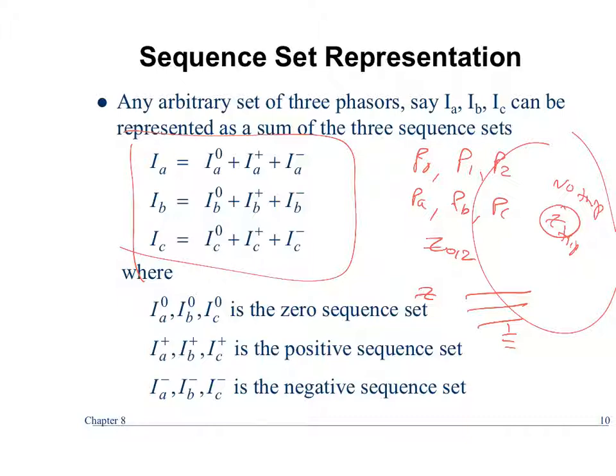Ground fault is so bad for using that you don't just rely on this 21 element, which is called, is it an impedance element? It's actually a distance element because how far you are away from a fault, right? So I'm a relay here sitting here monitoring for a fault. The impedance of the system changes as the fault occurs, right? When you see a load, there's a V divided by I, right? I get an impedance. If the fault occurs, it's going to shorten the impedance, right? So the fault is actually closer to you. That's why they call it 21, which is actually looking at impedance. They don't call it an impedance relay, they call it a distance relay.